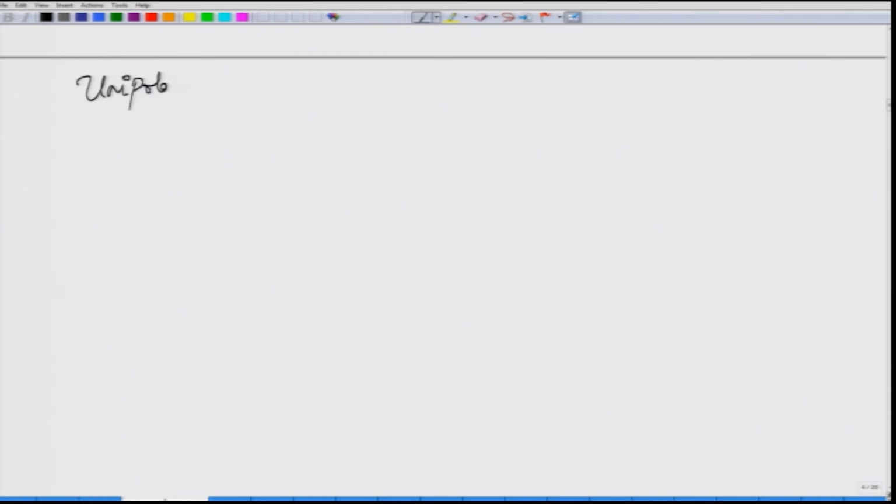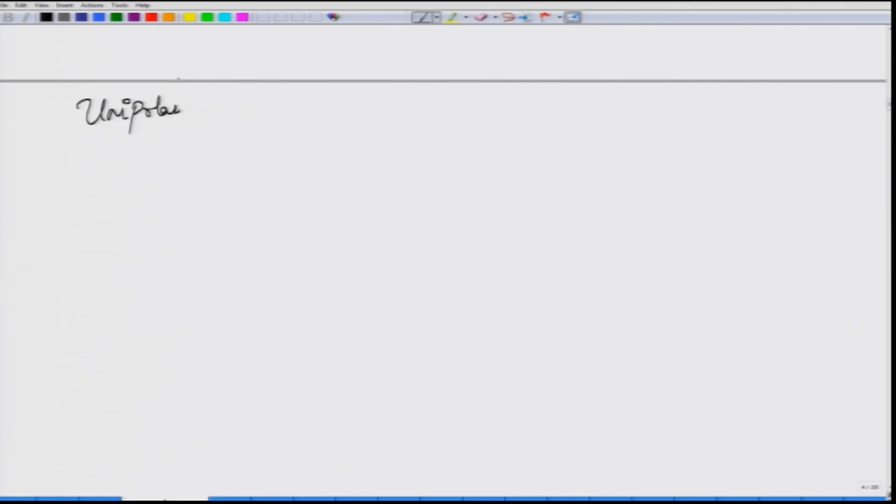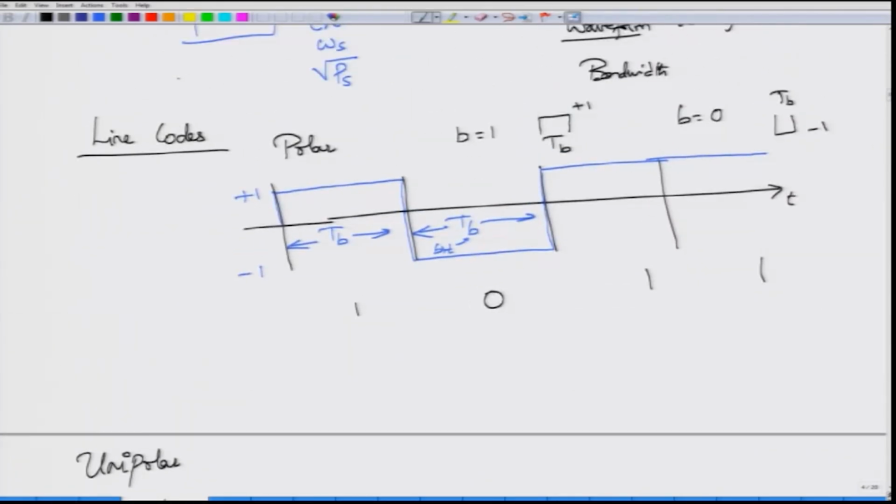You do of course realize that there is nothing optical about this one, at least until we specify that it cannot be optical. These are just regular line codes. Okay. How you represent a bit with a waveform. However, for optics there is nothing like a minus power. If for example, you want to represent optical power, as in intensity modulation systems, I can't have a minus 10 watt optical power, because optical power is always a positive quantity.